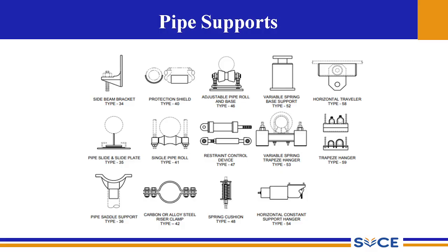So type 42 is using the shear lugs. Additionally, you have the lug supports which are used as additional welding arrangement. These load bolts will be used to transfer the pipe load to the rod hanger assembly.